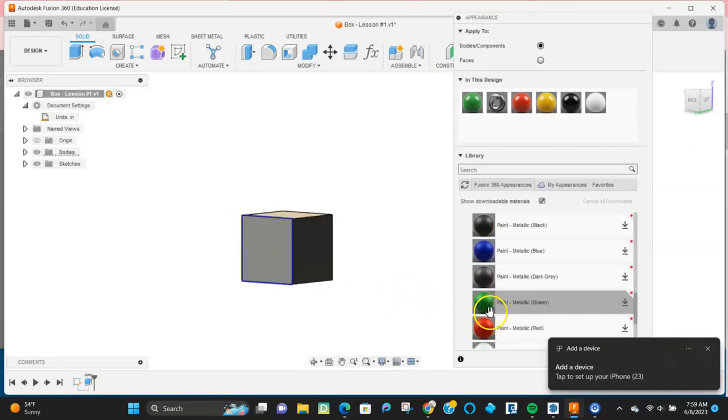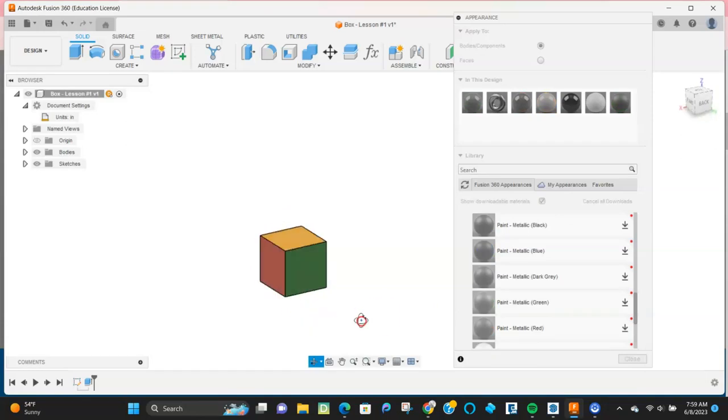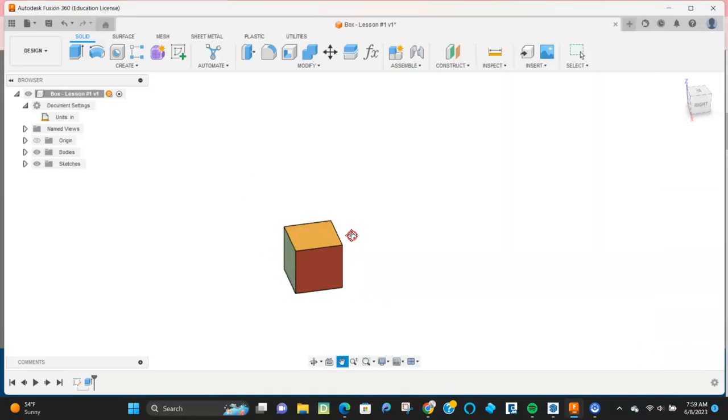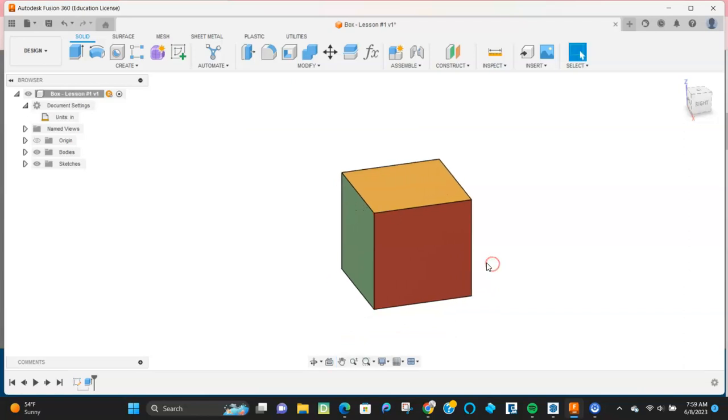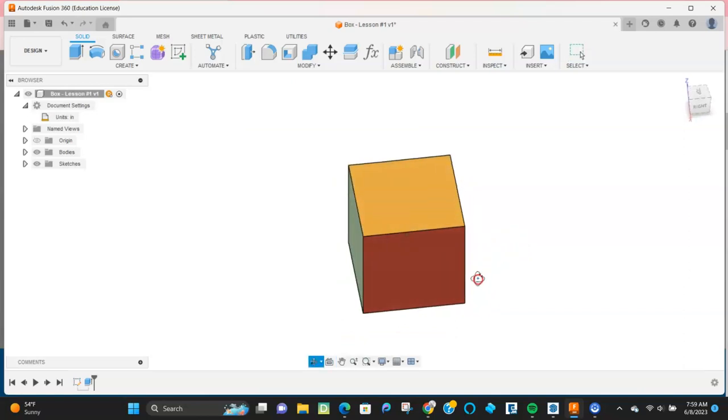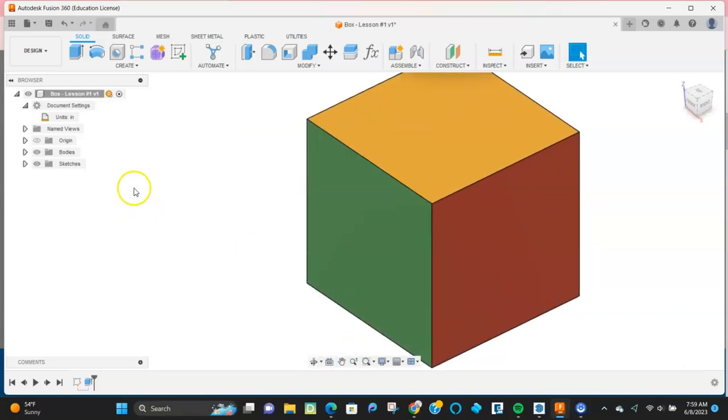But for right now, we're just going to put in white there. We'll know as a placeholder that it actually will be white. All right, so I have a cube that I can navigate around. The goal of this is to be able to navigate in three-dimensional space. So I have a cube. Again, shift and hold your scroll wheel to be able to orbit, and just push down your scroll wheel to be able to pivot.